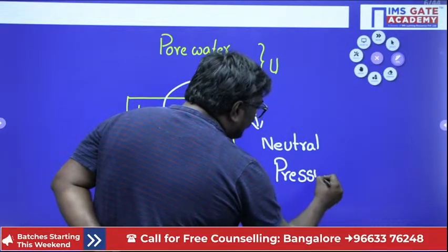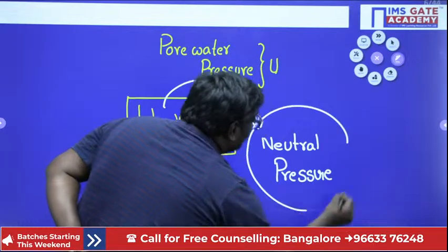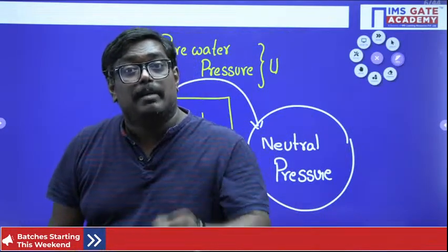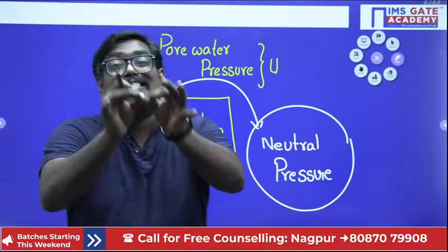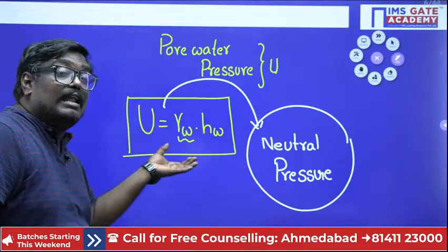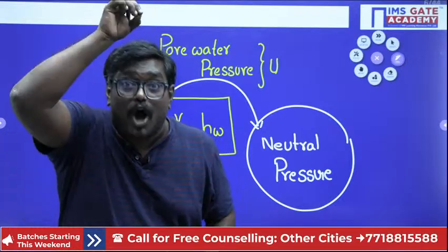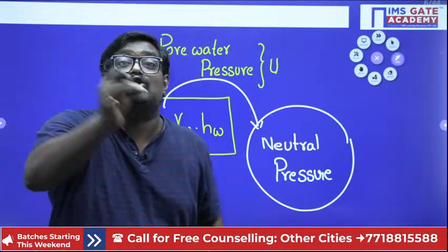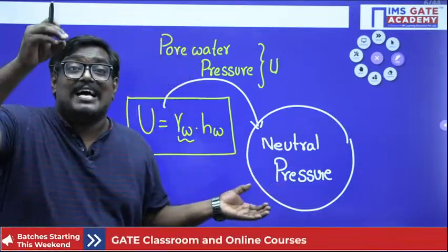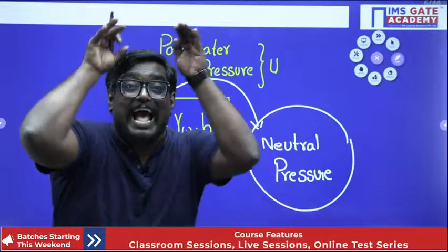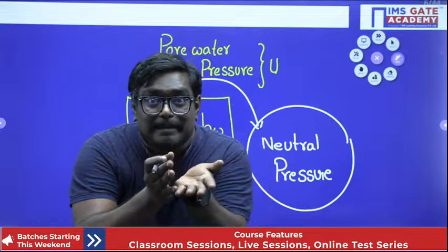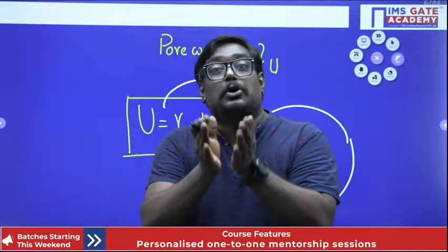Now comes the very, very important point which I would like to tell you. Students, whenever you are talking about soil, the stress taken into account is only the effective stress. You will never consider the pore water pressure. You will always consider the effective stress. Why? Because effective stress has an impact on the engineering properties, like permeability, shear strength or compressibility.